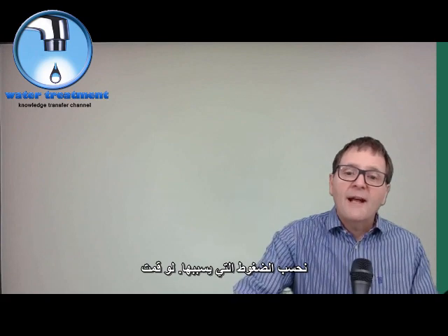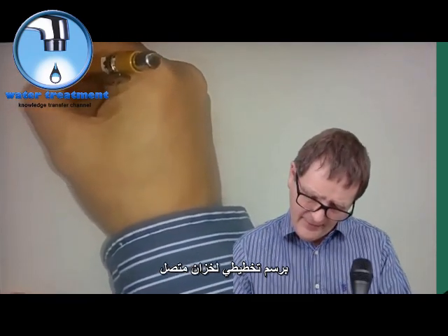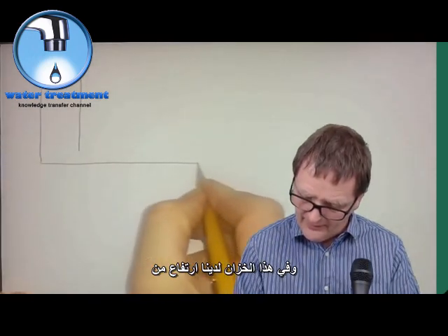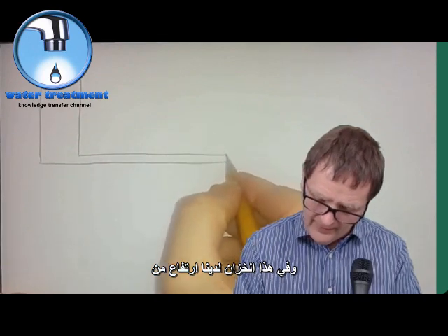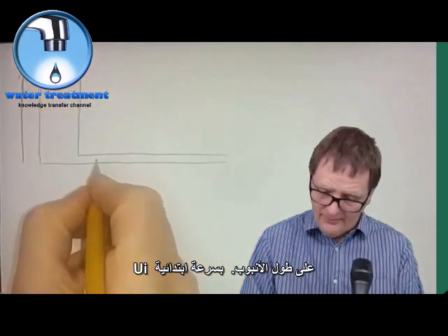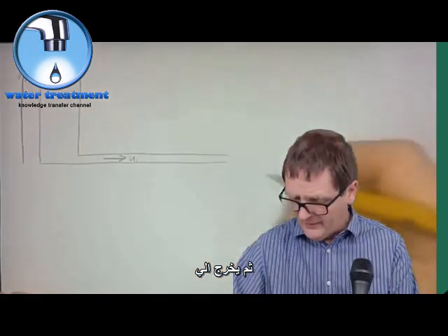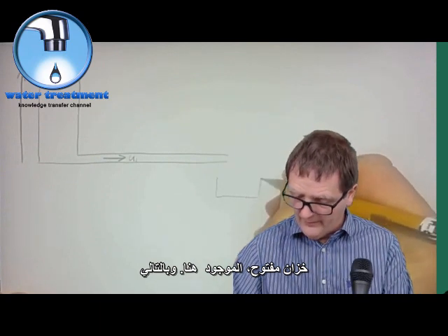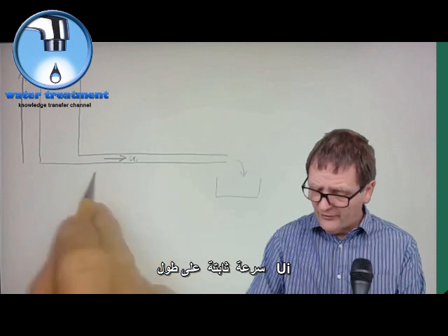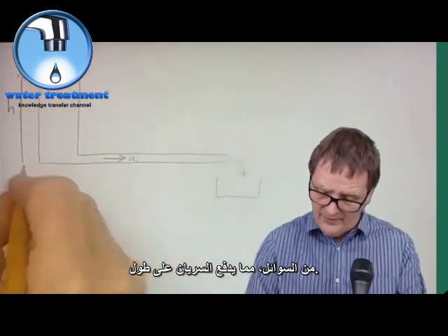So let me explain what is happening and how to calculate the induced pressures. If I draw a sketch of a tank connected to a pipe, so this is a header tank with a pipeline connected to it, and in this tank we have a head of fluid, and that is pushing the fluid along the pipe, and it's going to have an initial velocity u_i, and it's going into an open tank at this end here. So these are our initial conditions: constant velocity u_i along the pipe into a tank, and there's a head of fluid which is pushing the flow along.